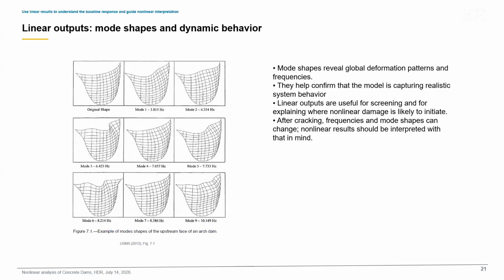The first output we usually review are the mode shapes of the dam, which shows the global deformation and frequencies. They help confirm that the model is capturing the realistic system behavior and gives us a baseline for understanding the nonlinear response.